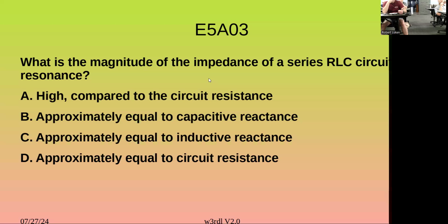But if you were to calculate the impedance, then R is in there, because it's R plus jX. So it's a vector, and the X is the phase-shifted reactance. It's either going to be 90 degrees or minus 90 degrees, depending on whether it's inductive or capacitive.